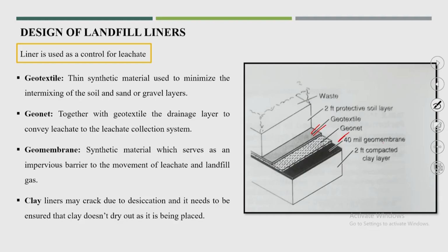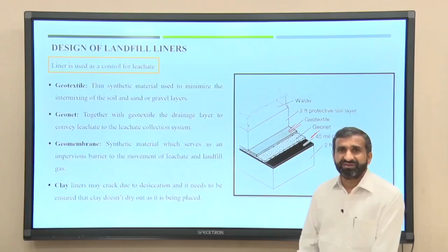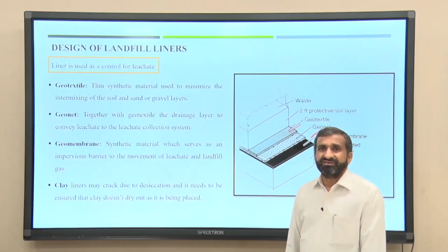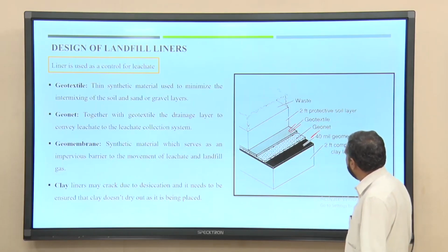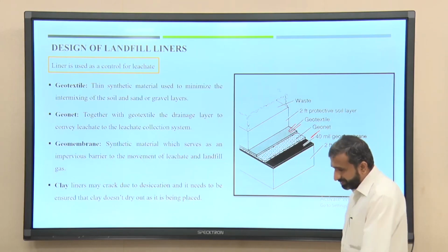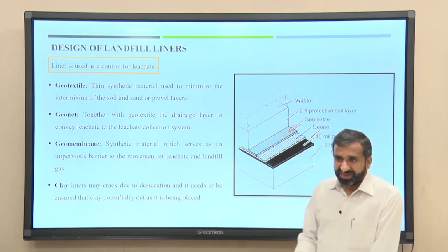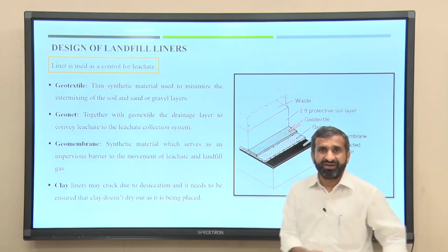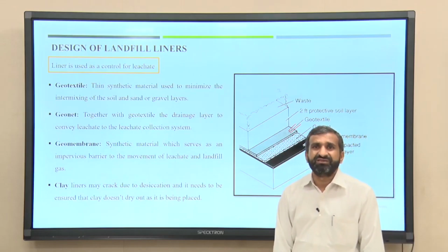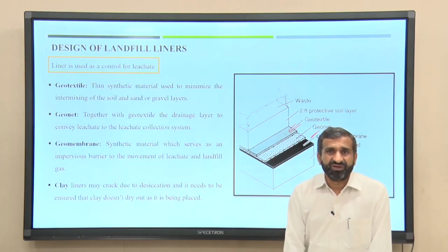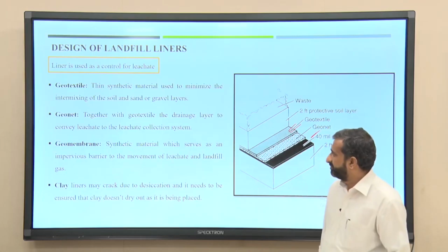But I think it is a very costly task. In most cases, wherever sanitary landfills are coming up in India, because units like geotextiles or geomembranes are very costly, what we are doing is we put a clay liner, gravels and HDPE liners. This is the common kind of liner we are using in India.